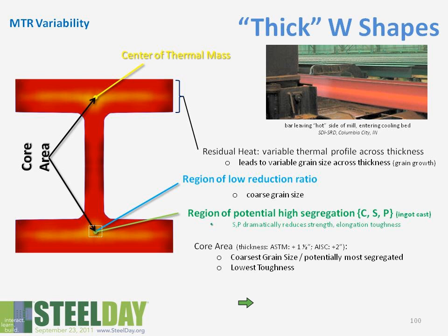You may be aware of the core area. ASTM defines that as 1.5 inches. AISC in the spec manual defines that as 2 inches or greater. Essentially, the core area, this box here, is an area where you have the highest thermal mass, so you're going to have the highest grain growth occurring.